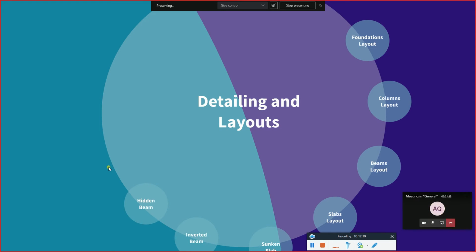Okay, returning back here. We said it's the same question normally asked whether we use solid slabs, or flat slabs, or waffle or ribbed slab, when to use this one. It depends on the economical point of view. I can use a 10 meter into 10 meter slab for a solid slab, but the depth is going to be too huge. If I went for 10 meter into 10 meter with a flat slab, the depth is going to be lesser. In that case, it's going to be more economical, so it's recommended to use flat slab. It does not mean that I cannot go for 10 into 10 meter with a solid slab. No, it means that it's not economical for that range of length and width.